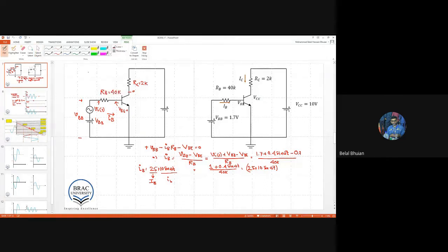We start from here, when we have a system where there is a DC voltage source and an AC signal source. So in that case, there are two signal sources present. One thing is clear to you: the base current that will be flowing is going to have two components. One is DC, another is 10 sine omega t, which is AC.